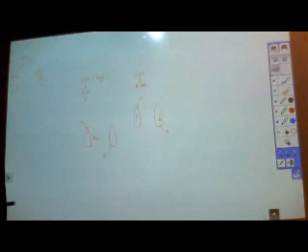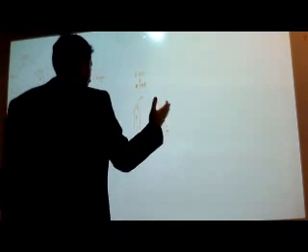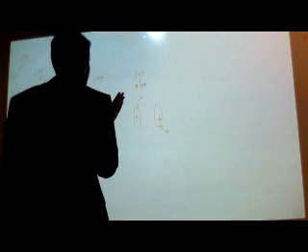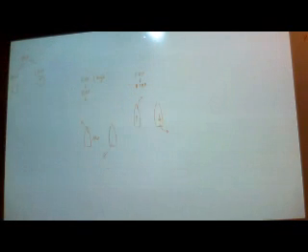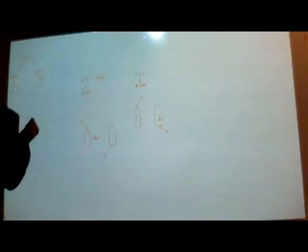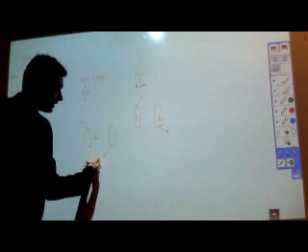How can you remember this? Well, use your hands. This is your right hand, and the way I remember it is, you see the curvature of your hand. When you go ahead, your bow is going to port. When you come astern, your stern is going to come to port. When you do it with the left hand, you achieve the same thing as here. Make sense?